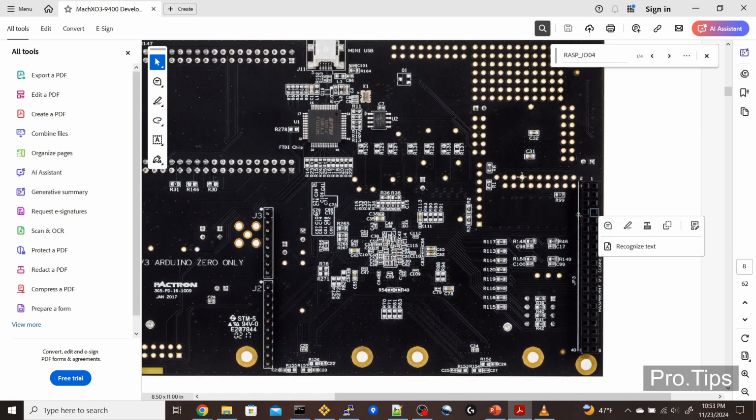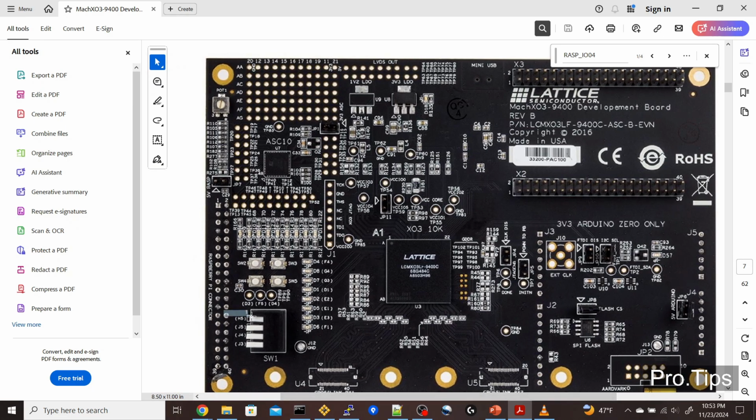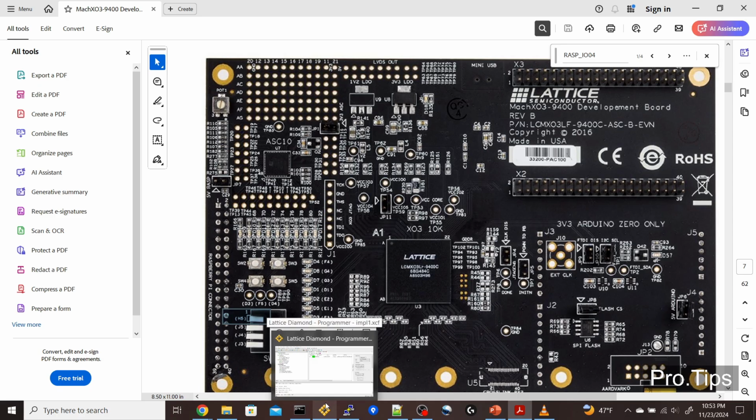So the last remaining is the reset input pin. For that, we're going to select the first dip switch, H5. This is an easy pick because a dip switch is what we need. So the reset will be 1 whenever this is not pressed. If it's pushed downward, the dip switch will go to 0 and then we'll be blinking the LED. All right, so we have the 3 IOs that we want to pick for our design.